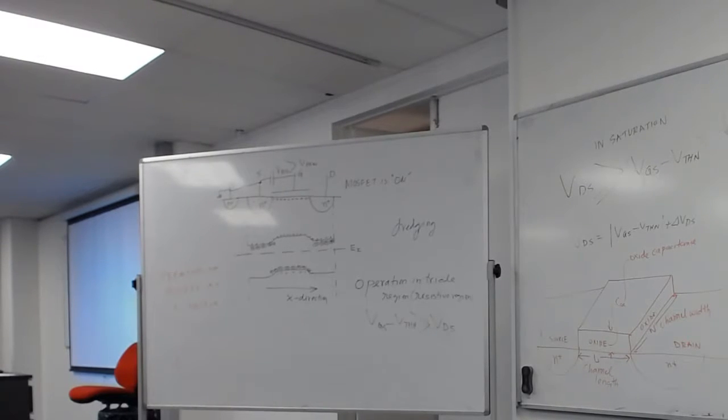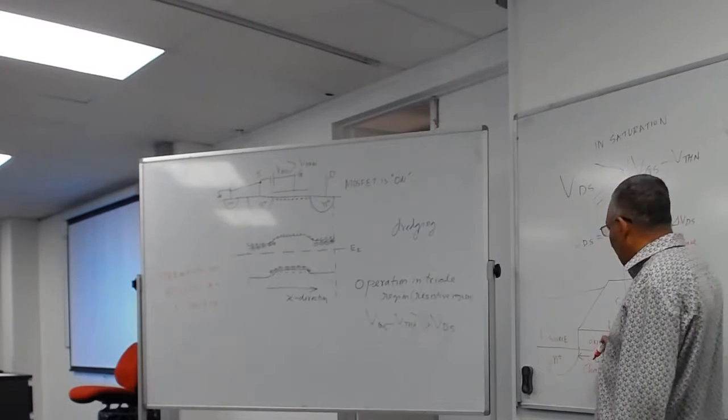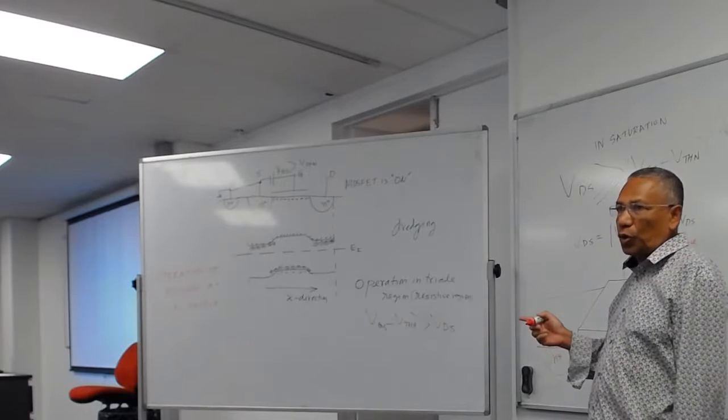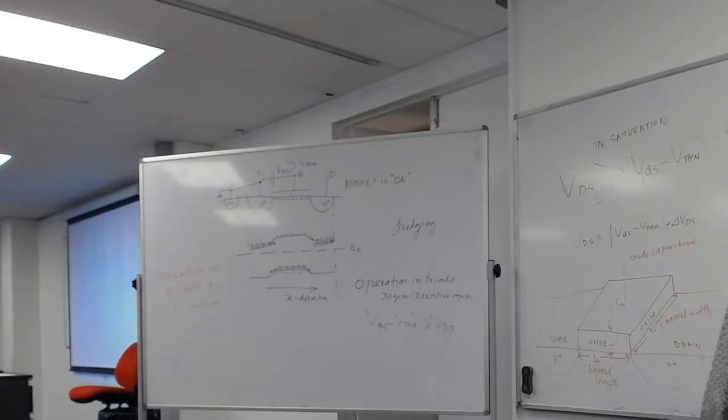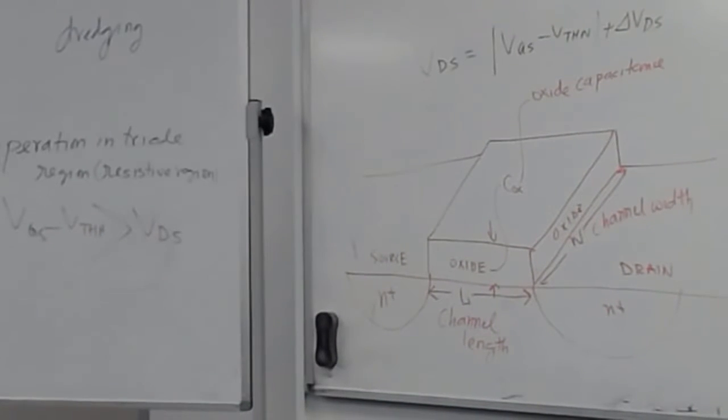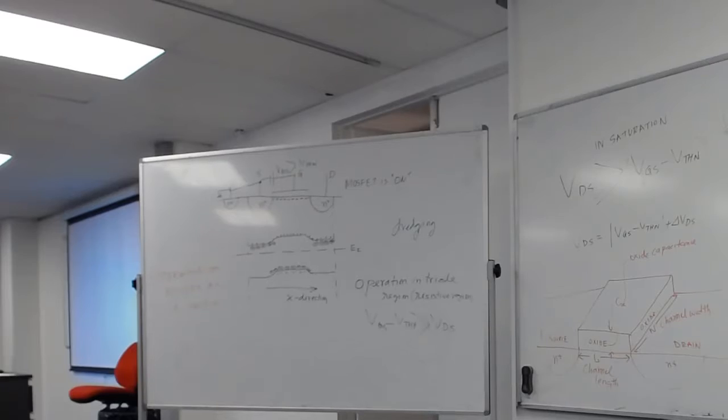Yes. Is there anything between the gate and source and the network? Nothing. You see, the gate is, that's interesting. Gate and source is oxide. Usually at the frequency that we're talking about, there's no current flowing. There's no gate current. So that's why it's vacant. That means the input impedance is infinity at low frequencies. So there's nothing there.